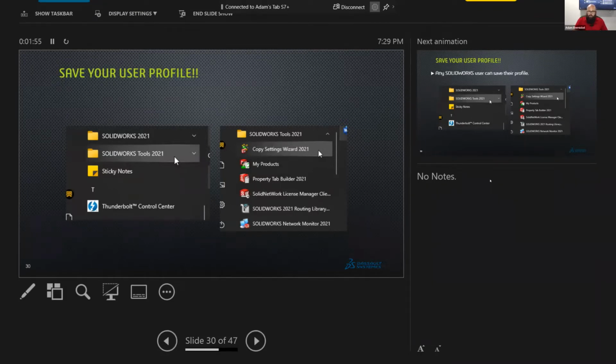I told him, as you go about your daily function, find out what tools you use the most. When you find out those tools, or you make a list of those tools, make those part of your mouse wheel shortcut keys. As a super user, I have that shortcut menu on each environment of my mouse wheel, in the same location, whether I'm in drawings, sketches, or assemblies. I can easily use my mouse wheel, go right over to a shortcut, or a different shortcut, and I have even more options. Reducing my mouse miles allows me to stay right where I'm zoomed in and focused, versus traveling all over the screen.